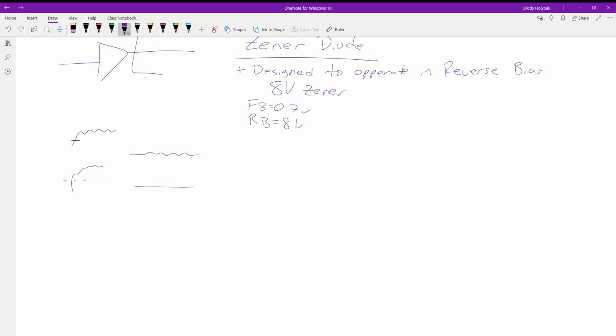And that's one of the things we'll find out when we get into AC, is AC raises all sorts of hell with calculations, because it is hard to dial into an exact specific frequency and an exact specific voltage. So your error is going to be a little bit larger in AC than it is in DC, because things are constantly changing.